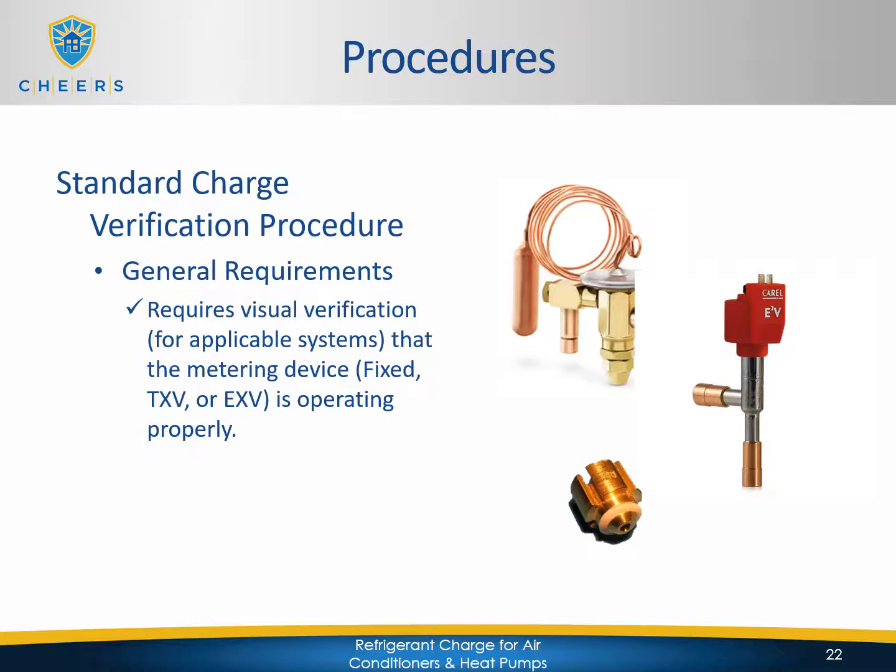Now these pistons will have different size orifices in them, and that's not something that you're going to be able to see or look at because it is within the system itself, but just so you know, different size coils will have different size pistons in them, and this will determine whether or not it's working properly, and we'll take a look when we do the superheat testing for this, because that's how you verify these. That'll let us know if the correct size piston is in there and if the coil is getting the airflow across it appropriately for the way it's set up.